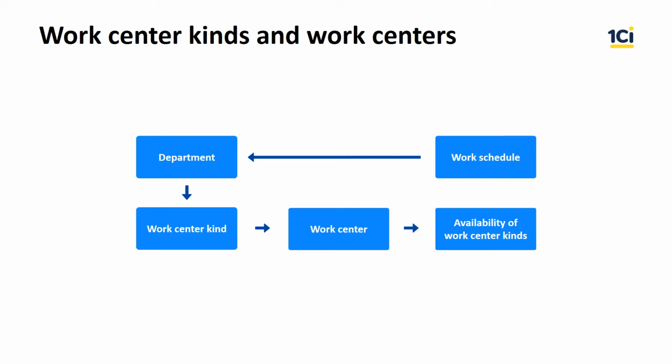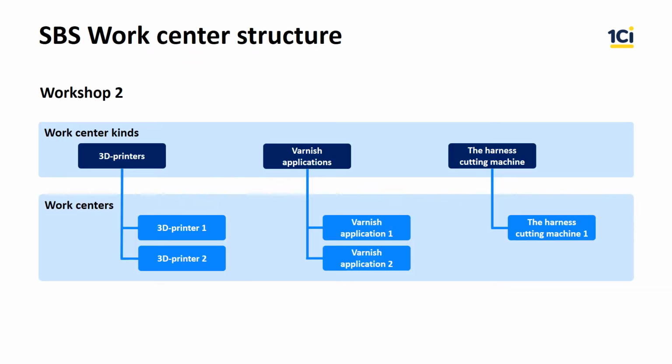The company follows the MRP2 approach. So, select the production management method, planning by material and production resources. To plan and execute technological operations, one's ERP introduces the concept of work centers. A work center includes an equipment unit and labor costs associated with it. Work centers can represent single machines, production lines, individual workers, production sites, and even entire workshops. To enable using work centers, select MRP2 using the Planning by Material and Production Resources option.